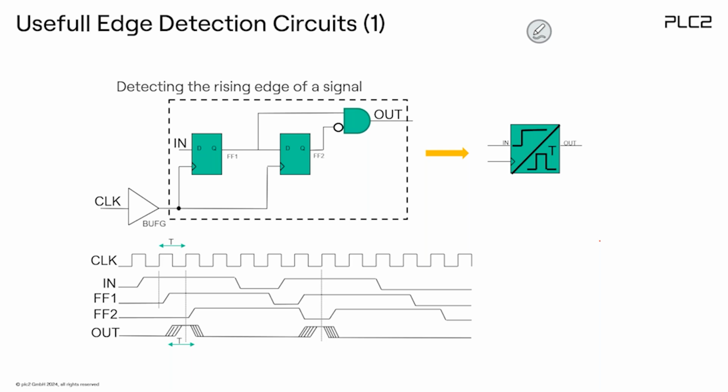We have an input signal here, for example, but instead of using this signal as a clock, we run it through the edge detection and provide a pulse, which in this case would be the rising edge. Whenever there's a rising edge here, we get a pulse which is completely synchronous to the clock. So you can do the analysis very nicely.